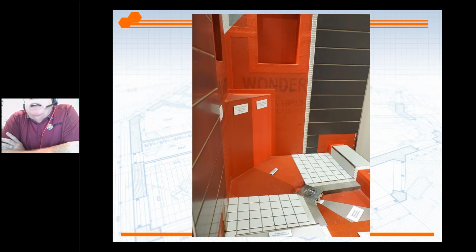As we started doing a lot of tear outs, we found that a lot of moisture was being held in these mortar beds. Sometimes they're too tightly compacted. Sometimes the weep holes are blocked. The tiles, and especially natural stone, sometimes looks very dirty. We've actually gone back and cleaned some and asked them not to use the shower for a while, and it'll dry out and clean up. And then as they start to use the shower again, moisture will accumulate underneath there.